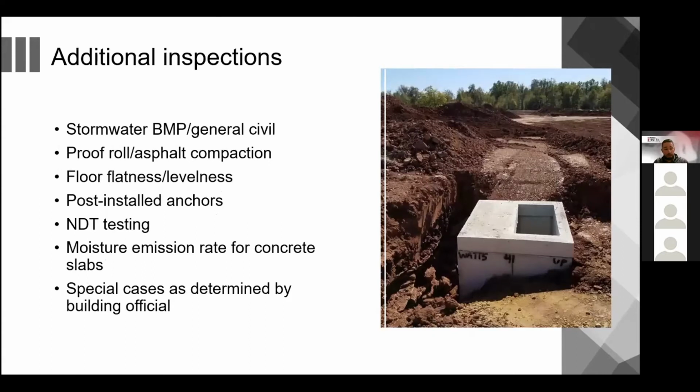Additional inspections as well: stormwater BMPs, pipe and utility installation, rain gardens, infiltration beds, inlets, ESC controls, proof rolls, and asphalt compaction. I already discussed floor flatness, pull tests, maybe post-install anchors as well, but we do pull tests on those. NDT testing, Windsor probes, or